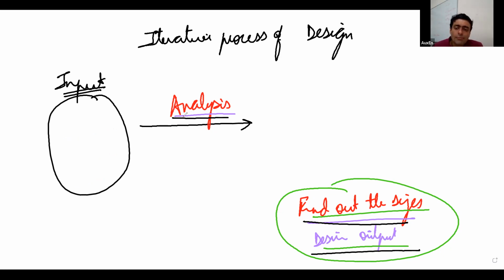And why so? Because unless you give some section properties, unless you give some section sizes, your analysis will not be performed. Why will your analysis not be performed? Because all these systems are indeterminate or redundant systems. So the stiffnesses of these systems play an important role in the analysis outcome.